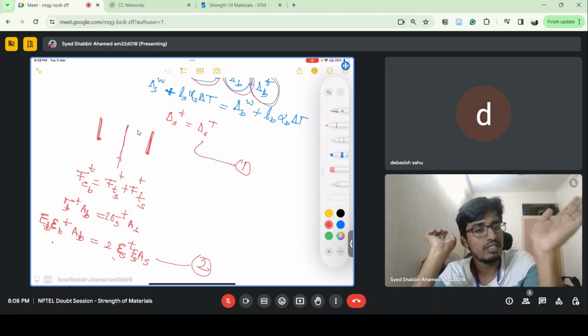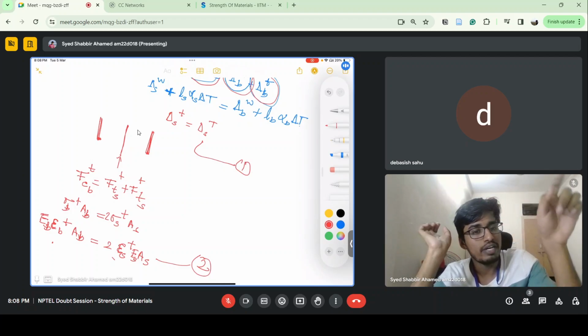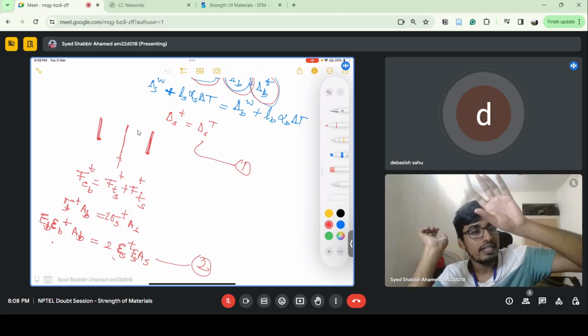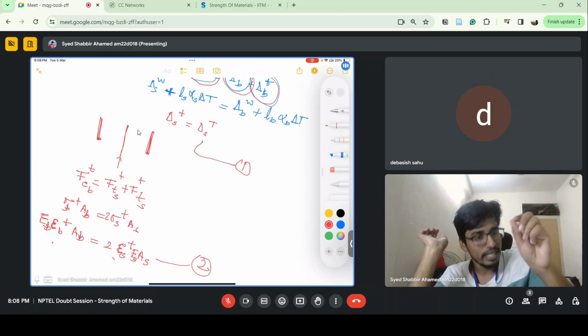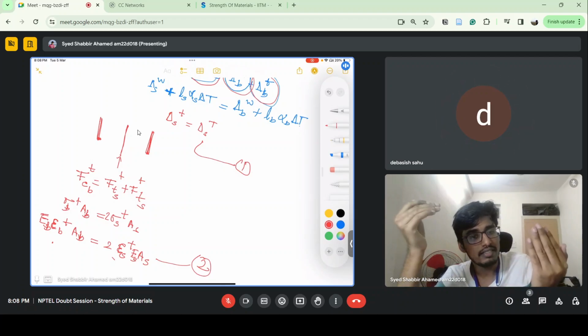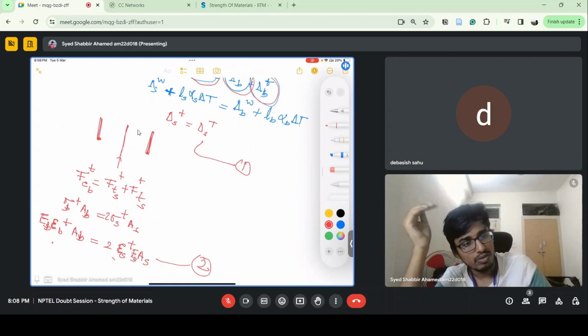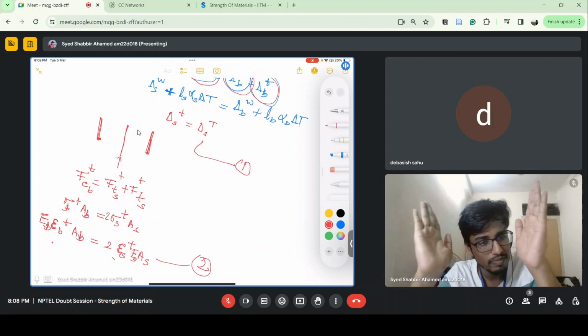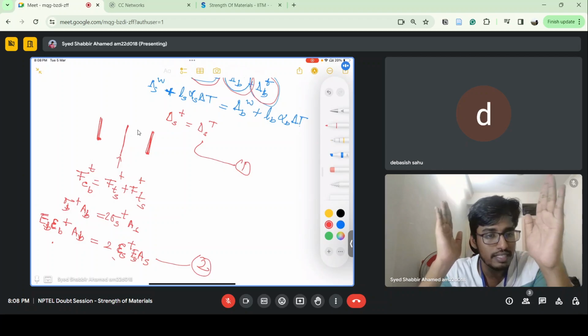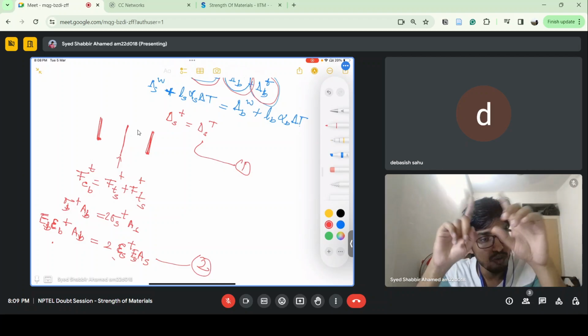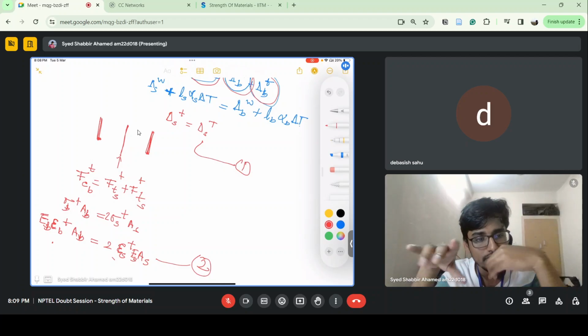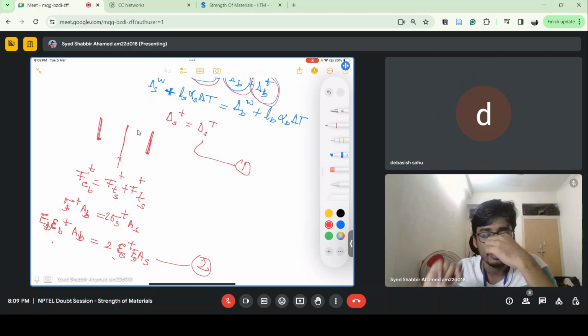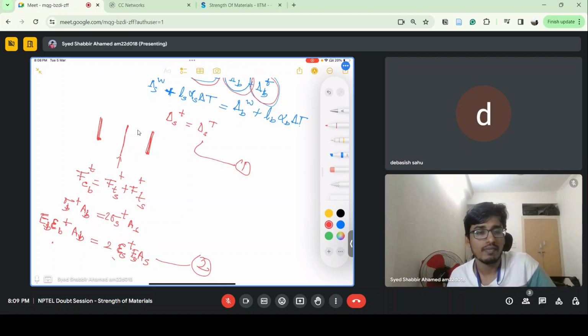So the displacement gradient and small displacements are calculated. From that, you can get the strain. So digital image correlation is done for getting the strain field. For the whole field you can get the strains, so at every point you can get the strains. Got it?